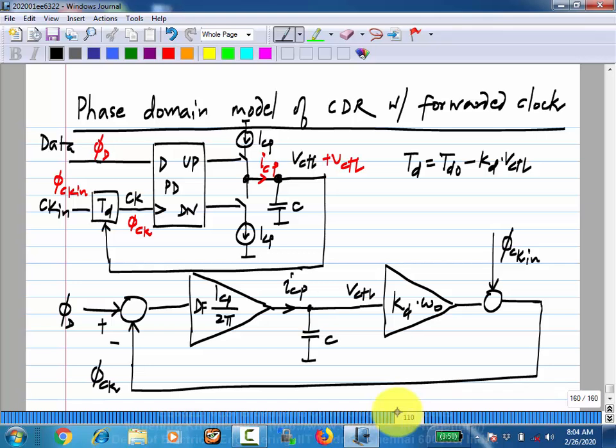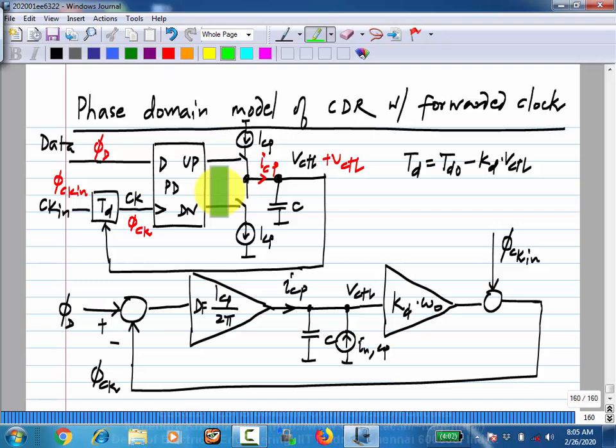So any questions on how we derived this or any aspect of this? Now we can add more things here. For instance, these current sources used to make the charge pump will have some noise, okay. So we can also add that to see what effect they have. I will call it IMCP. So that will be the current noise of the charge pump, okay, effective current noise. Now we have two sources which are switching. We will discuss that. I have modeled the entire noise as an additional current at the output of the charge pump, okay. So now please calculate the following in this.